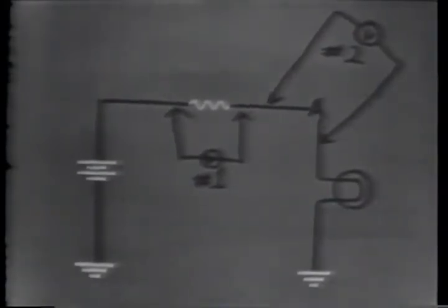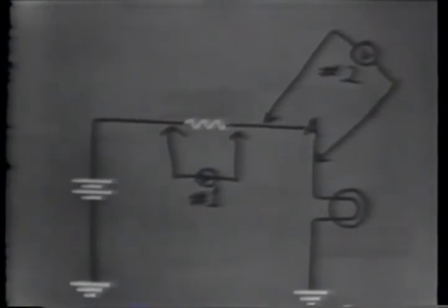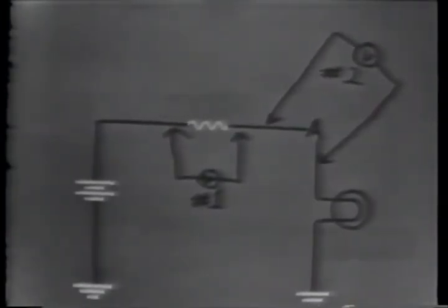You can see by connecting the voltmeter across this point, it will complete the circuit, which will allow a small current to flow. The resistance of the voltmeter is much greater than that of any other component in the circuit. So, in effect, it will read all of the applied voltage. If you were to connect the voltmeter across the lamp, you would get the same indication as you would across the resistor. Again, the reason for this is the open does not allow current to flow.